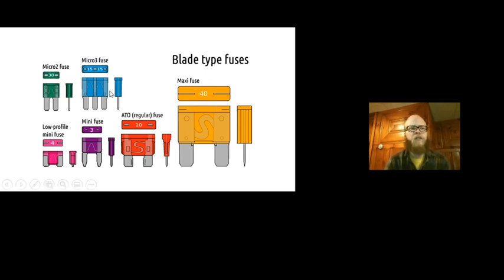There are also these fuses where it's two fuses, but there's only three blades instead of, if we had two fuses, we'd have to have four blades. These are a space saving item. They're trying to fit more stuff into the same size fuse panel. The problem with these is if one of the circuits pops, well, then you have to replace this whole fuse, and it costs more than just a regular fuse.